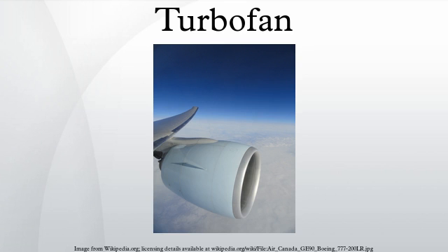Because modern civil turbofans operate at low specific thrust, they only require a single fan stage to develop the required fan pressure ratio. The desired overall pressure ratio for the engine cycle is usually achieved by multiple axial stages on the core compression. Rolls-Royce tend to split the core compression into two, with an intermediate pressure compressor supercharging the HP compressor, both units being driven by turbines with a single stage, mounted on separate shafts. Consequently, the HP compressor need only develop a modest pressure ratio.